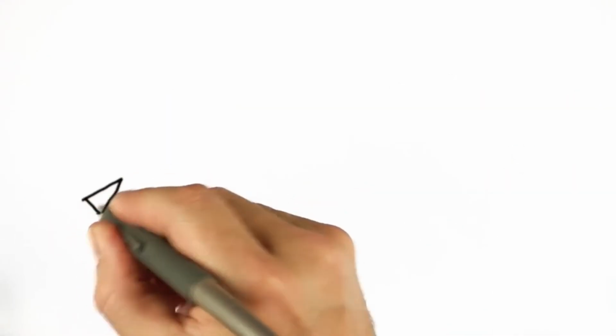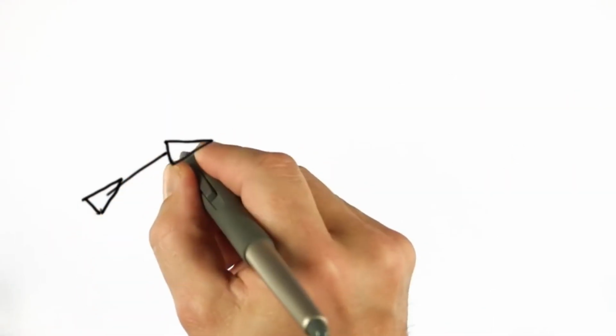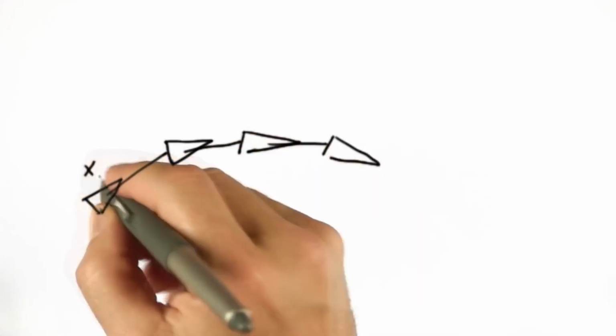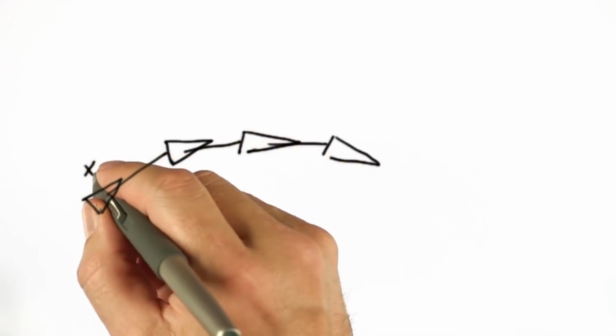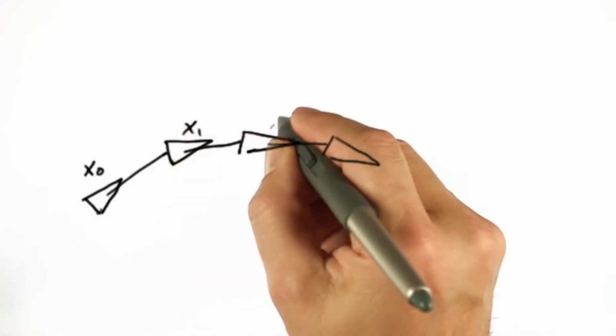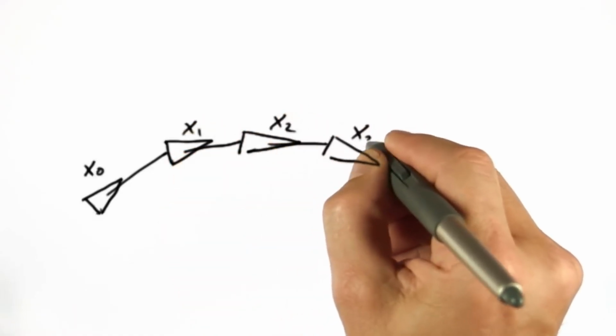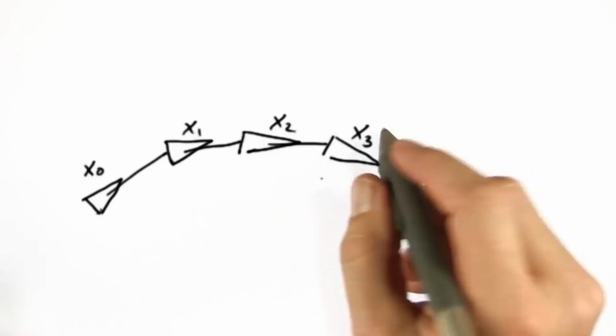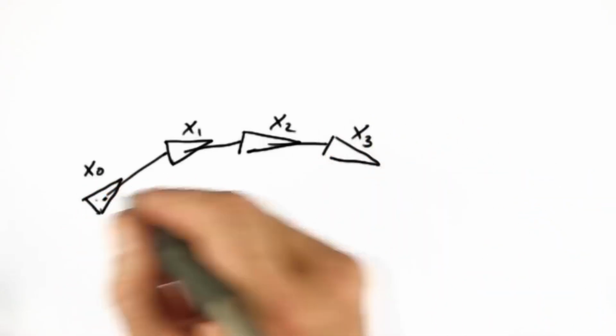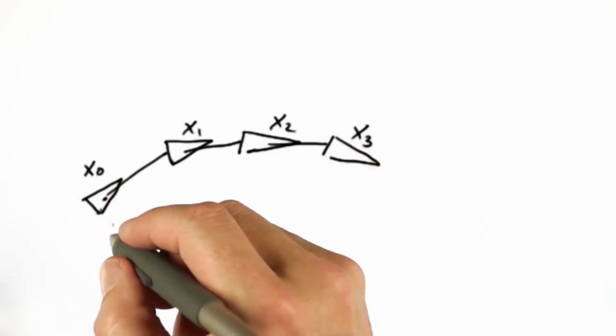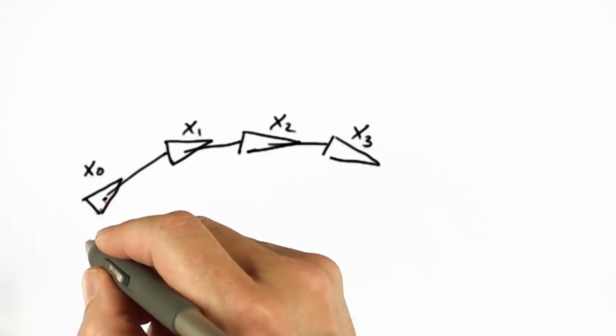Say we have a robot that moves in some space, and each location is now characterized by a vector x0 and a vector x1, vector x2, and vector x3. Often they're three-dimensional vectors. Then what GraphSLAM collects is the initial location, which is just 0, 0, 0 usually, although here it looks a little bit different.